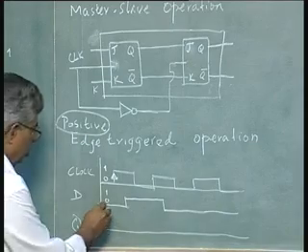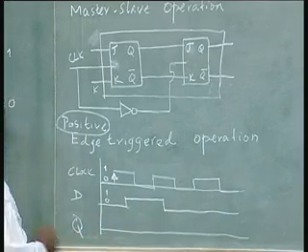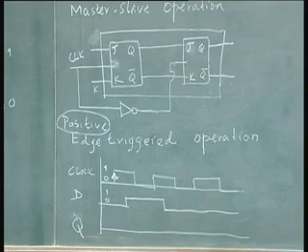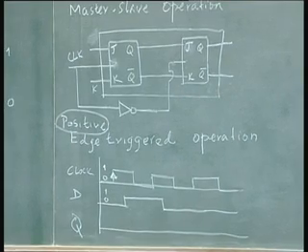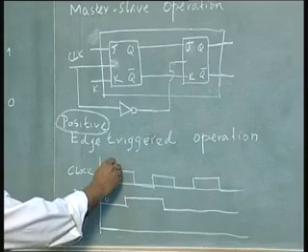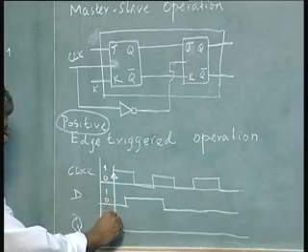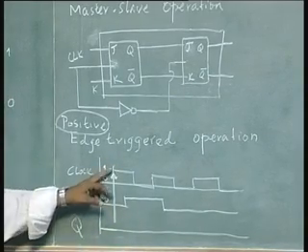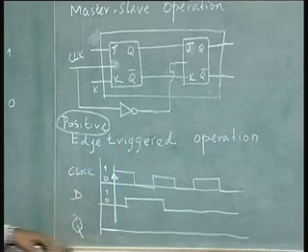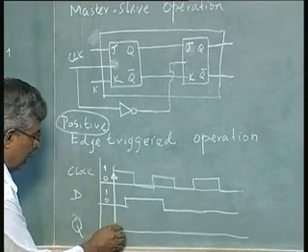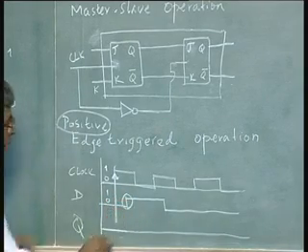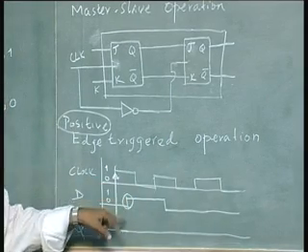So now let us assume the flip flop output was a 0. At every transition of the clock, the flip flop circuit will look at the input, which continues to be 0. So nothing happens. The D input has changed from 0 to 1 at this point. Will this affect the output?